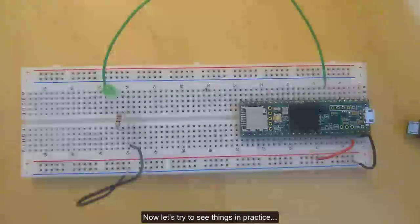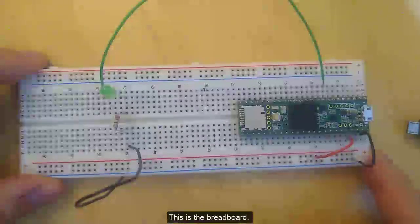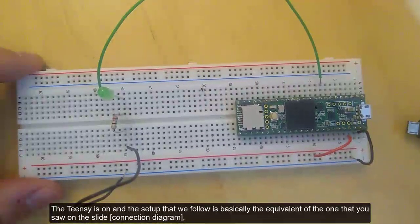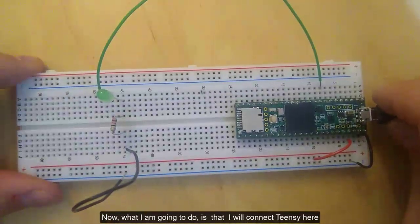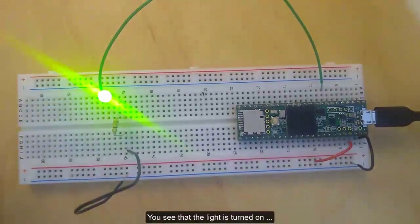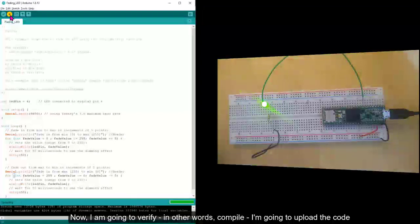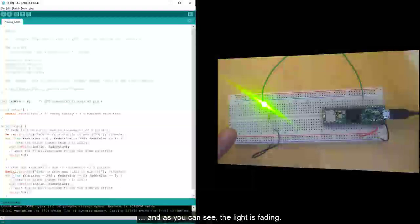Now let's try to see things in practice. This is the breadboard. The Teensy is on, and the setup that we follow is logically the equivalent one of the one that you saw on the slide. Now what I'm going to do is that I'm going to connect Teensy here. You see that the light is turned on. Now I'm going to verify, in other words compile. I'm going to upload the code, and as you can see, the light is fading.